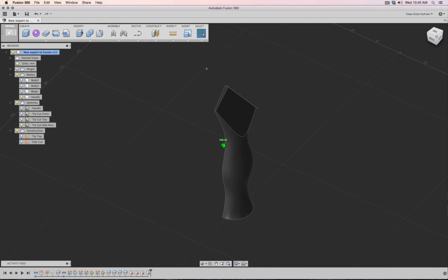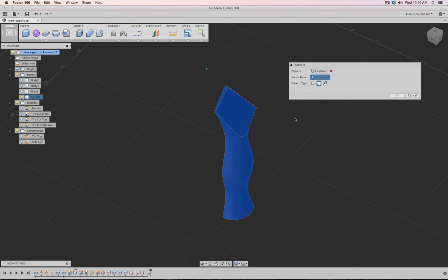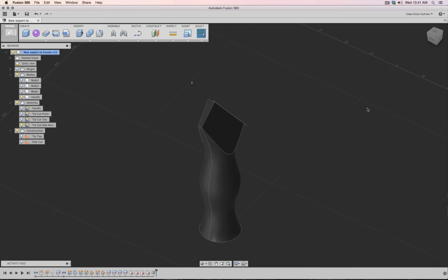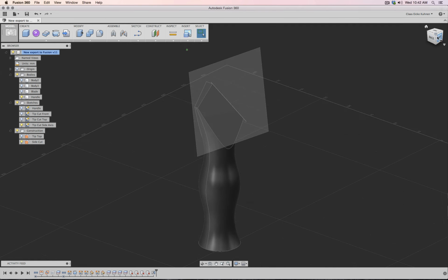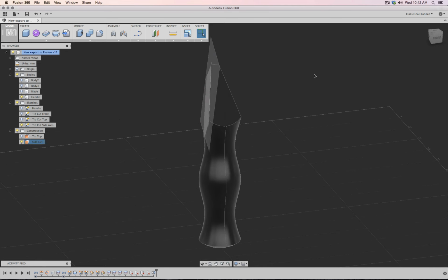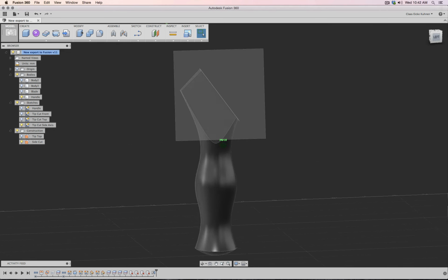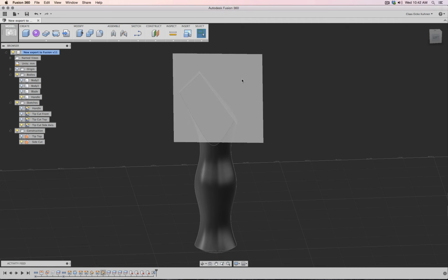Okay, let me pause for a second because right now I would have to see how I could actually change the steps so I have a little bit more control in how to cut the side at an angle. And of course, the moment I hit pause, I figured out how to do it. I'm using this plane. This plane already has the correct angle from here and also rotation, but I'm using the complete plane and I want to restrict the cutting not to be the complete plane, so an infinite space, but just an area.